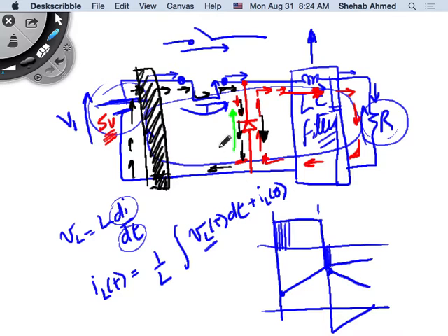Because of something like this, not just this characteristic, there will be other things that we talk about later, but this is one of the reasons we will do something like that, right? If we do this filtering, then we will treat the battery better. We will allow this to happen because we know that there are certain times where there are significant changes in current and voltage required by the load, and we will use a filter to make sure that we handle that properly. We will talk about that later.